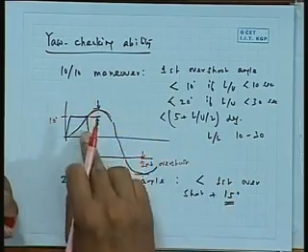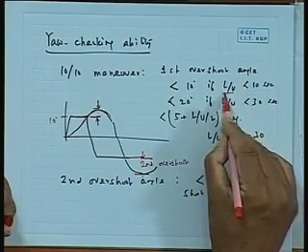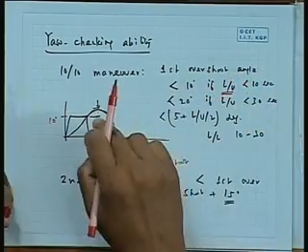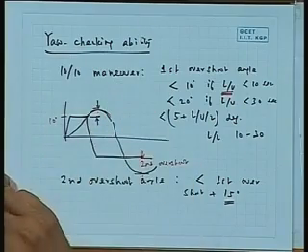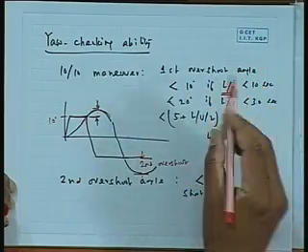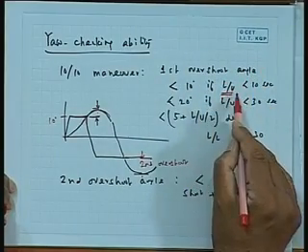Now this is given a stipulation with respect to 10 degrees if L by V is less than 10 seconds. Now you may ask why L by V? This is because it is found that this overshoot is obviously connected to speed also. So if it is a higher speed, you expect a larger overshoot angle. That is why they have given this L by V criteria. If you think of a fixed L, V is increasing, then L by V is decreasing.